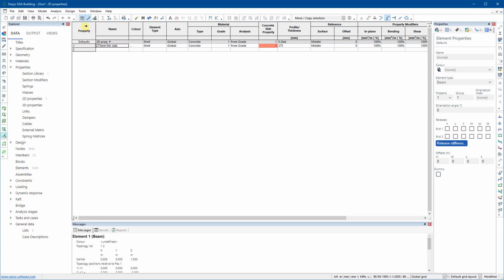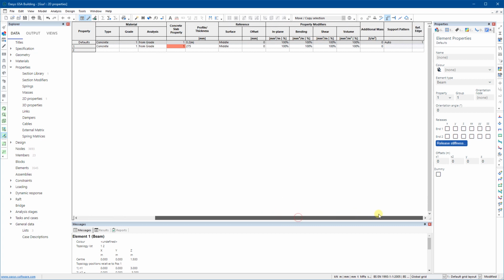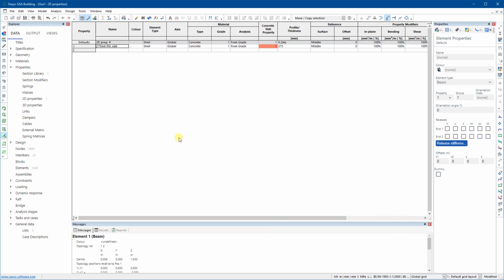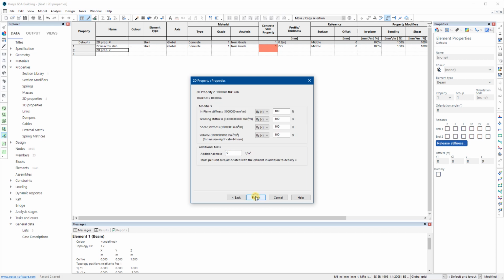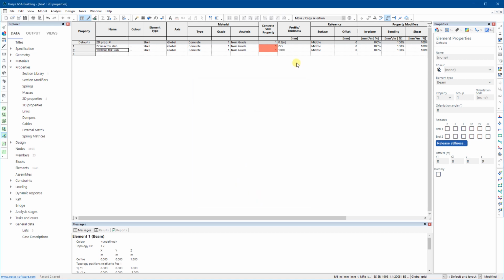So that's my name. It's property. So property, it's a 2D element. So it's PA, an area element. So property 1 is the 275 thick slab. And that's just the properties that we've input. So all fairly straightforward. Just for interest or reference, I'll put in maybe a meter thick slab. Like so. So again, and this one is property 2.